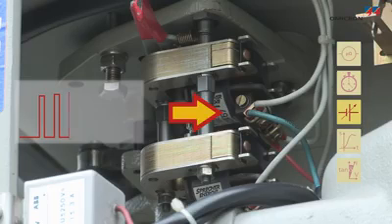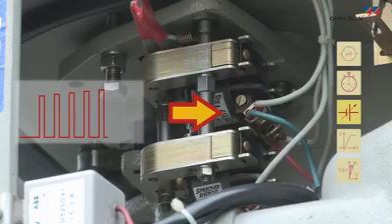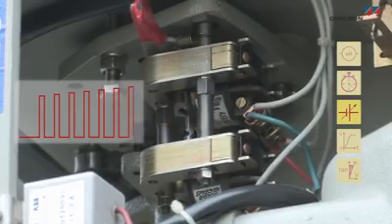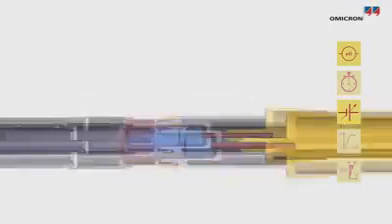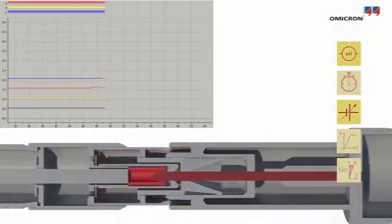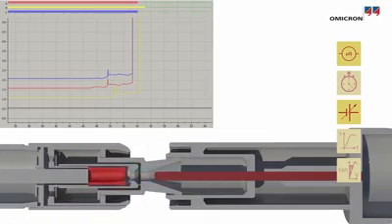The minimum voltage, known as minimum pickup, needed to trip and close the circuit breaker is also usually measured to ensure that it can still operate in case the DC supply is weak. If the breaker is equipped with a multiple contact system, measuring the dynamic resistance during opening and closing will indicate the wear of the arcing contact.